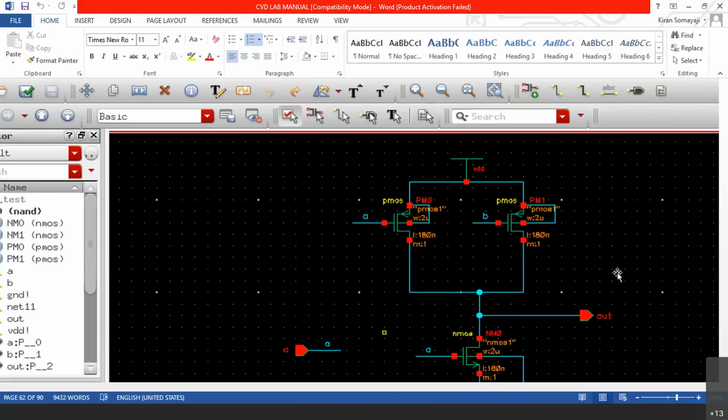That is because the layers are arranged like that, sir. Metal first, then there is an oxide layer between the two, and then the conductor is there. See, metal is there only for VDD. Otherwise, source is not metal, drain is not metal, it is diffusion. Metal is only there at VDD. Oxide is there between gate and channel. Oxide is not there between source and drain.